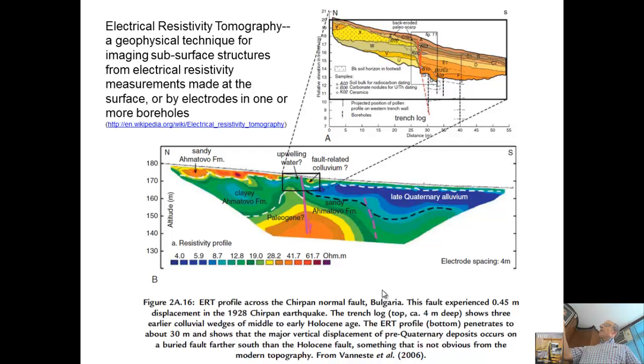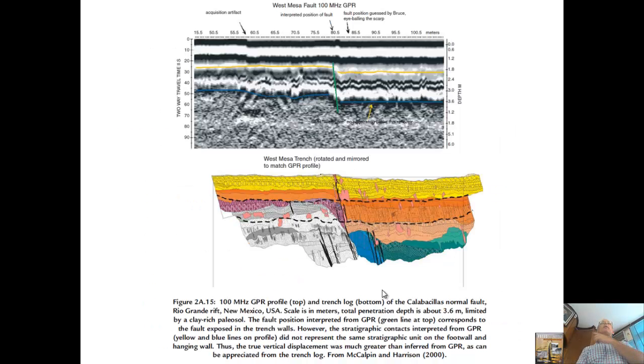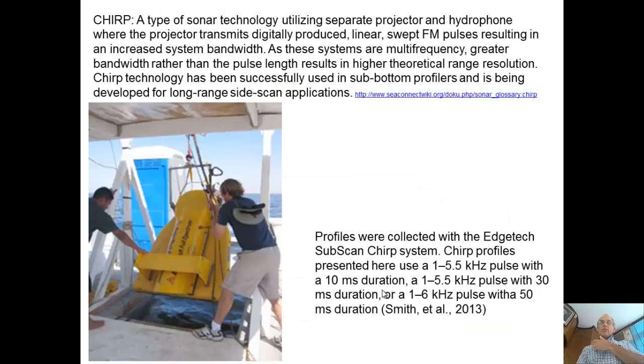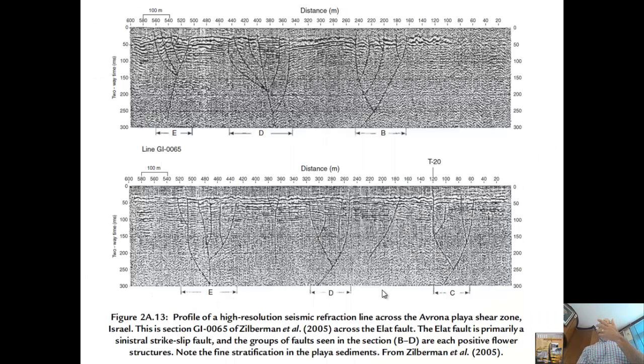Like this electrical resistivity is going to be very sensitive to, especially, the groundwater. So you can almost always tell if there's a barrier of groundwater because the wetter side will be more conductive. But then maybe you get good reflections from your georadar, but usually georadar has low penetration, whereas then you may try, okay, we get good penetration from our seismics, so this gives the depth. So what would be good is to try all three methods at that place.